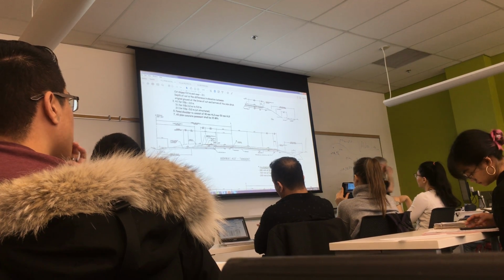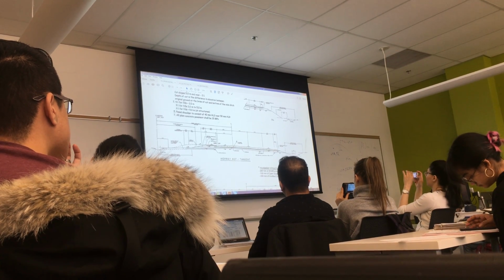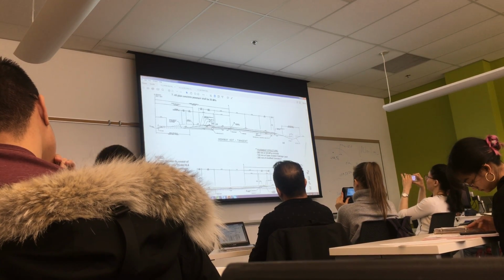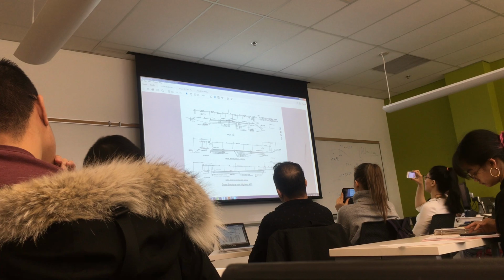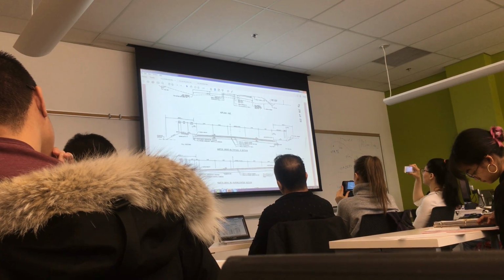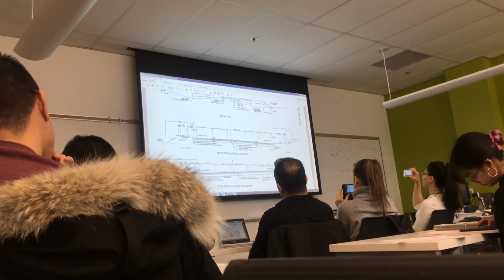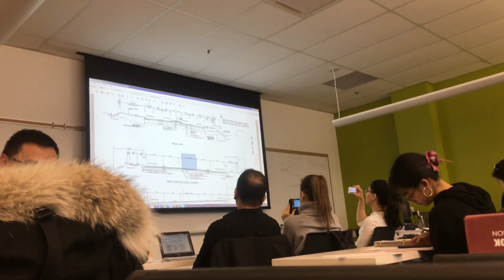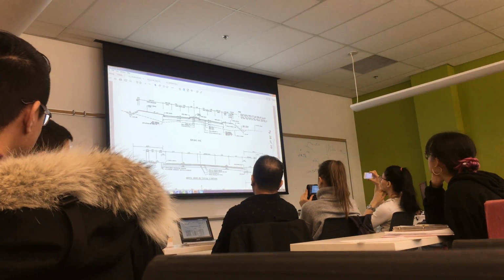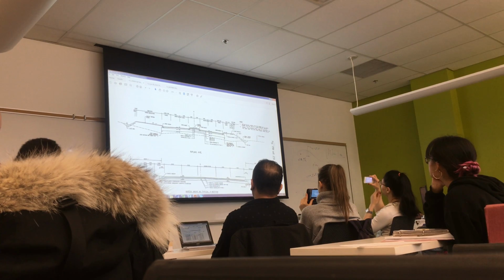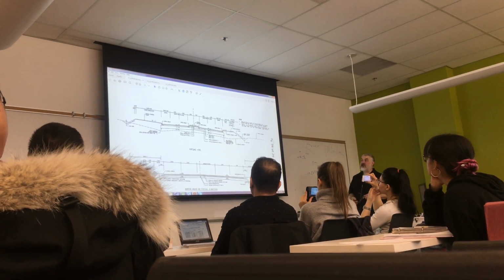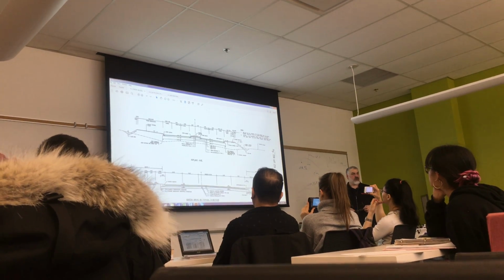There are a lot of great examples at the back of the booklet in terms of drafting standard, what to show. Here's a super elevated section. Here's a tangent section. If you go back one more page, there's a couple more examples. Super elevated urban. Here's an urban section with a turning lane. And here's one divided with a median in the middle and so on. Everything you need to draw it was annotated on the drawing. And if you needed it to draw it, then the contractor needs it to build it. So put it on the drawing.